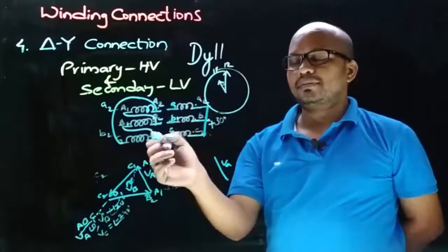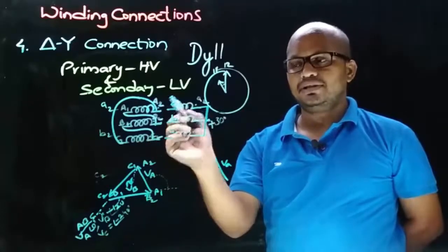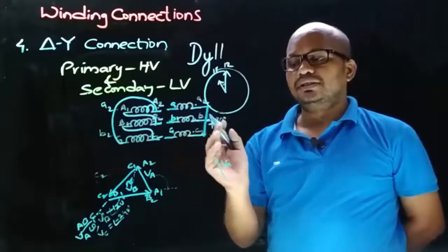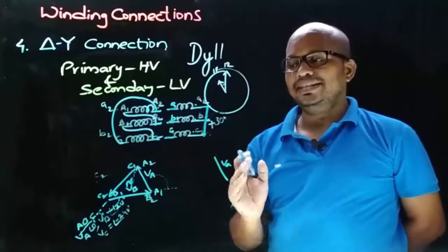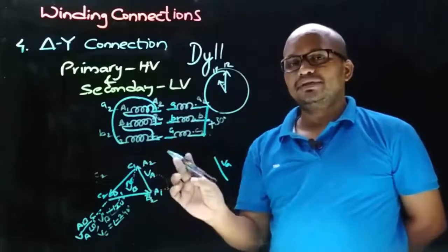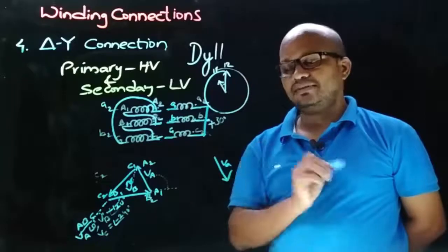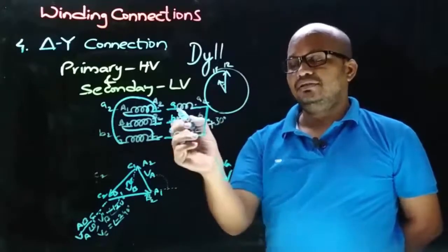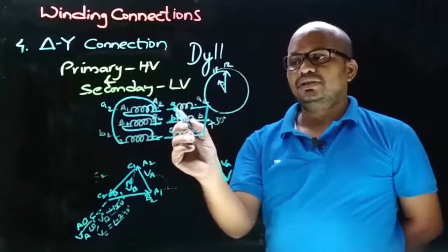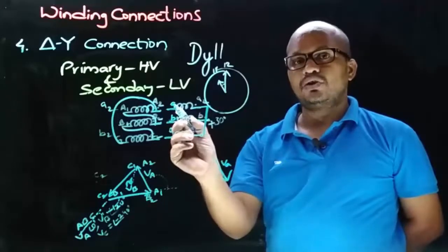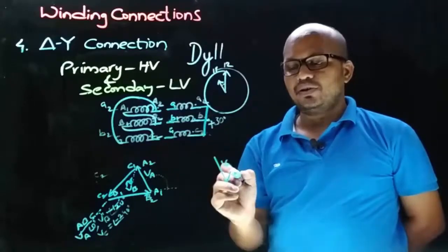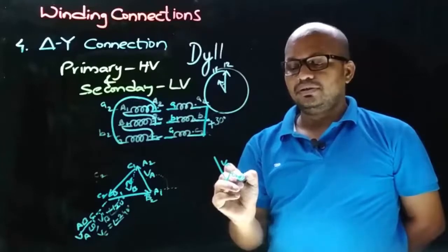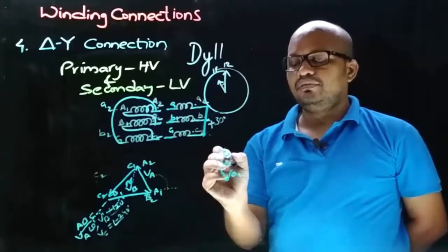Therefore, observe that on the primary side connections are taken from dot end terminals, and on the secondary side connections are taken from non-dot end terminals. Therefore, the direction of the secondary side VA phasor will be opposite to the primary side VA phasor. Therefore, the direction will be like this. Now, let's decide the terminals of the secondary side VA phasor. Here in the winding connection, observe that the connection is taken from the non-dot end terminal, that is A1, as the arrow will point towards the connection we took from. Therefore, the terminal here is A1, the other end will be A2.